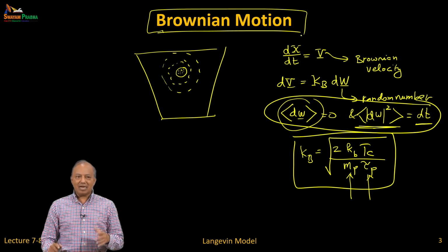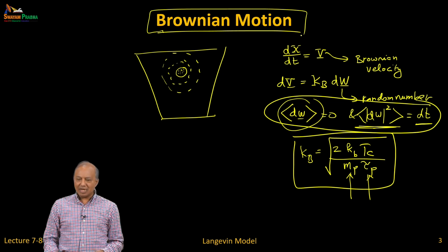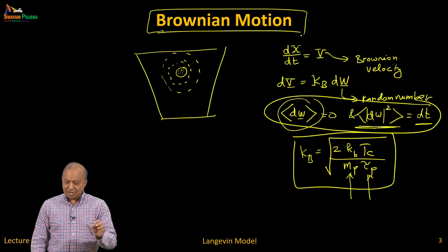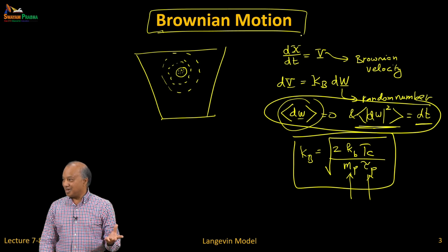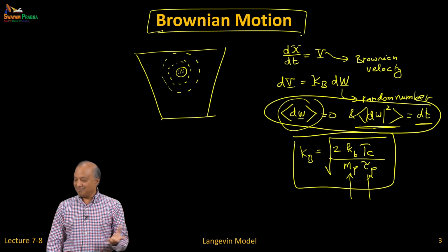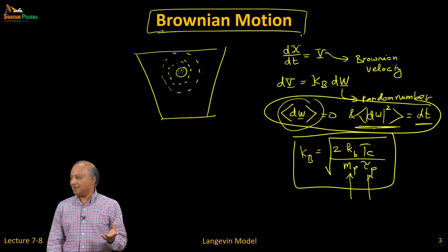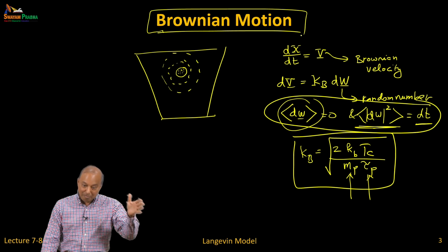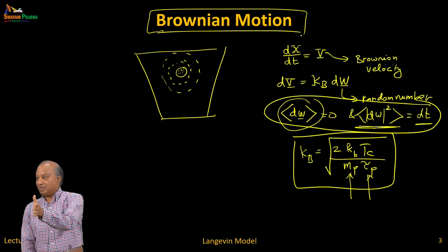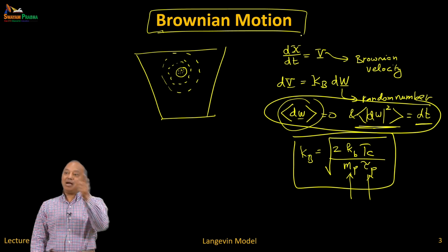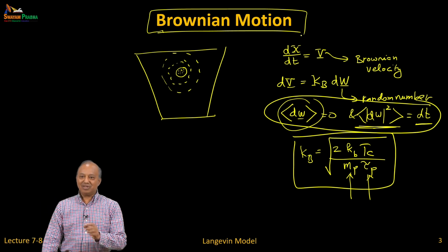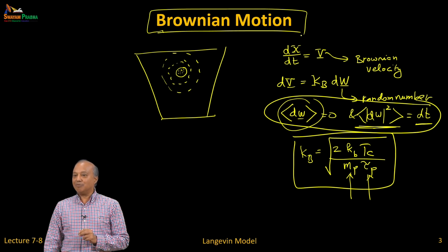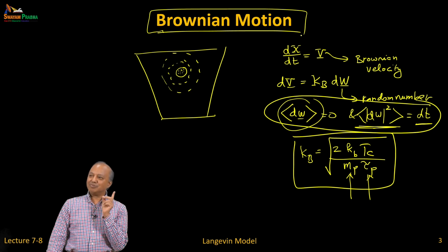But this gives you an idea how to do this, and this is what we're going to do in the Langevin model. Here there is no bulk motion, so that's why I wanted to start with this. There is no fluid motion. Particles just keep getting random kicks each time. But when you track particles in the previous slide, a channel flow, there is a mean flow which tells them to keep moving downstream, so you have to add that. On top of it, we are going to add this idea. One catch, however, is that our random numbers now must have some memory of the previous time step.